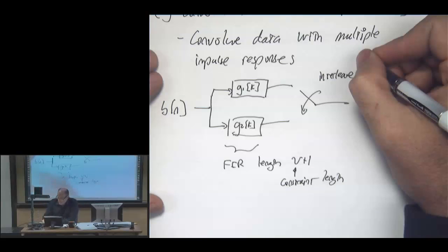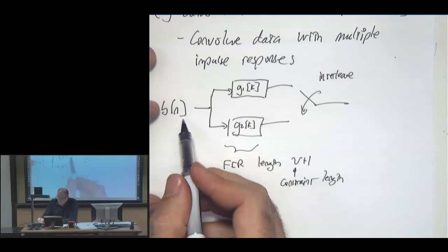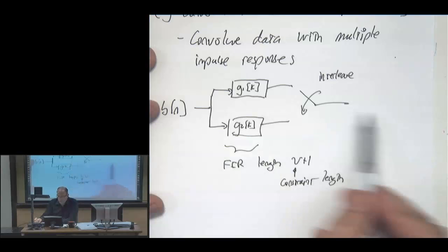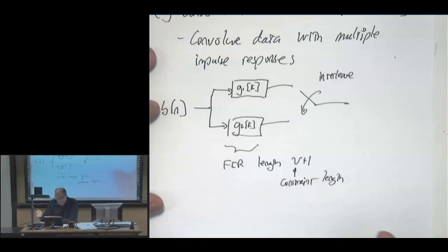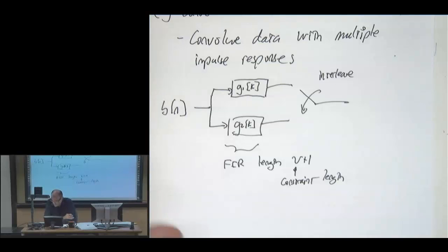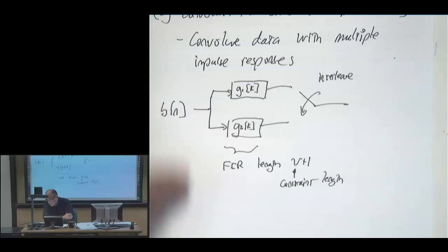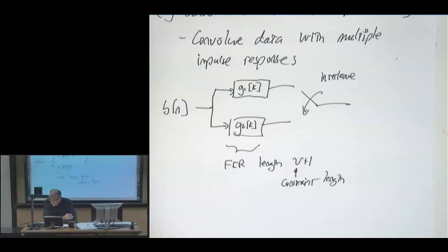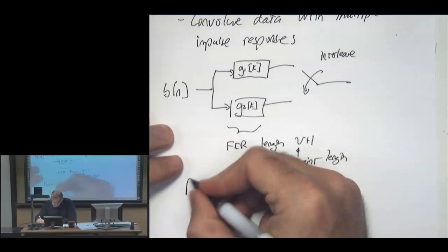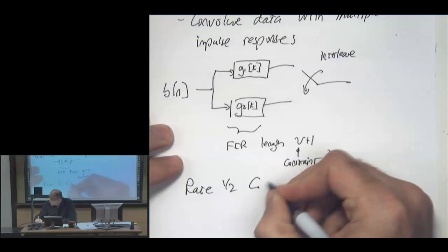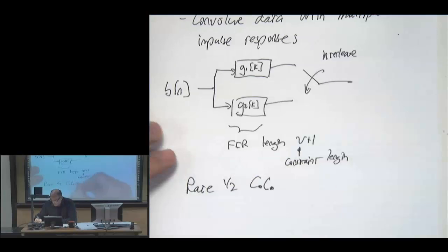And so you can see that this bit stream creates 2 filtered versions of that bit stream that we then end up interleaving together. And we have a little bit of a tail, too. There's various ways to deal with that tail, and usually you initialize these with zeros. So that's an example of a rate 1/2 convolutional code. And there's many variations of this.